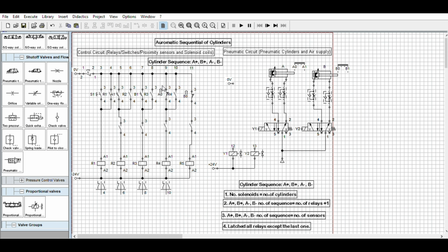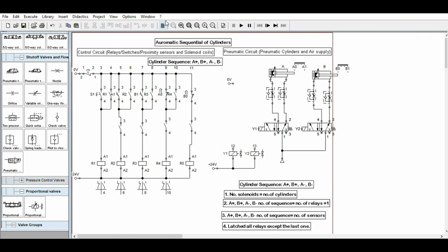They have this symbol because they are represented by initially triggered. Initially triggered means this sensor is initially open, but when placed near to the cylinder, it is triggered, becomes closed, that symbol. Okay, so the differentiator is that it is normally open, but initially triggered, it becomes closed because it is near to the cylinder head.